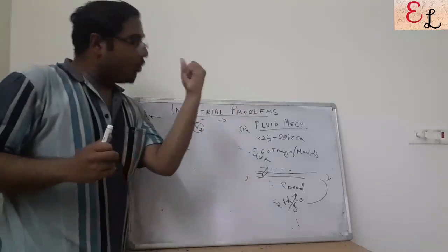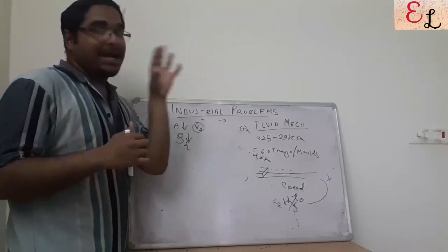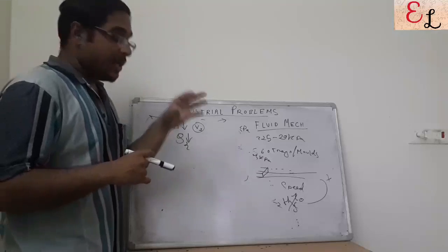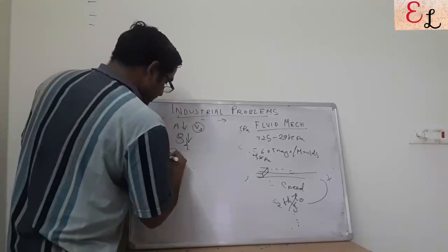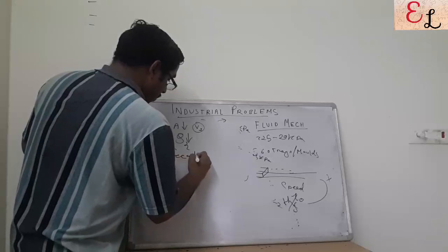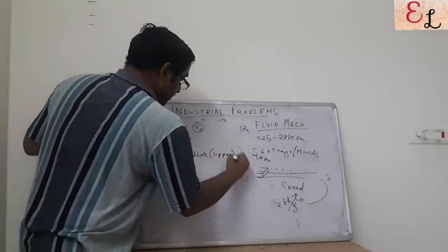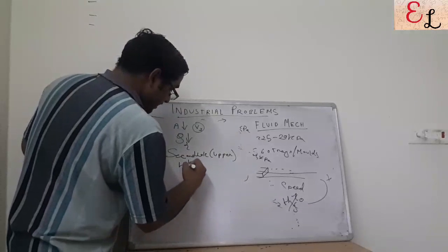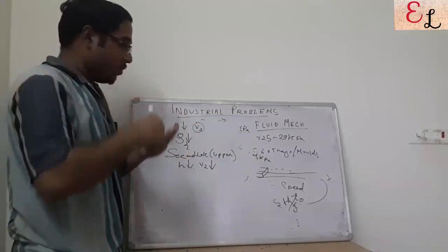Second suggestion was, they were tapping from the lower hole, tap from a higher hole. A higher hole tapping, what would it do? It would ensure a lower bed height. It would ensure a lower H. Due to a lower H, a lower V. So use the second hole, upper one to be used such that H decreases and V2 decreases. That is, the height of the slag bed above the tapping hole decreases.